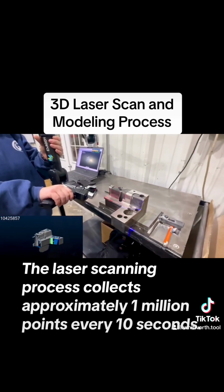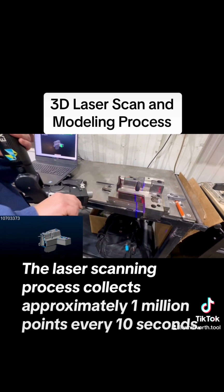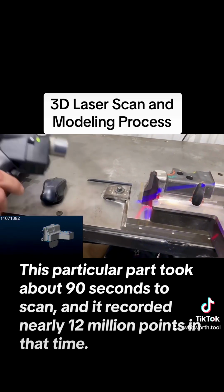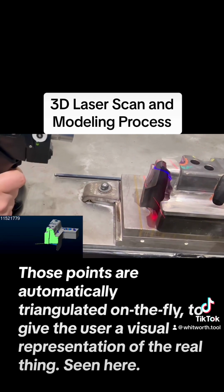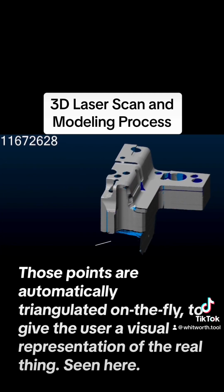The laser scanning process collects approximately 1 million points every 10 seconds. This particular part took about 90 seconds to scan, and it recorded nearly 12 million points in that time. Those points are automatically triangulated on the fly to give the user a visual representation of the real thing, seen here.